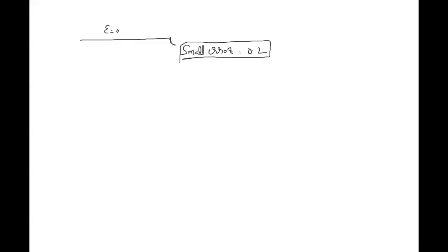So there is a small error of 0.2. That might not be because of a process upset. Sometimes these measurements are also fluctuating. So if it is a proportional controller, it doesn't respond at all. When Kc is equal to 0.1, it doesn't respond at all. This is the P controller.